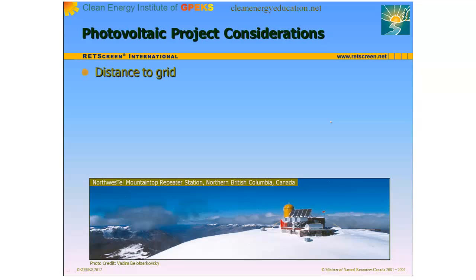If the grid is near, within a few kilometers, and the load large, more than a few kilowatts for example, photovoltaics will have more difficulty competing with grid extension. When sites are remote or difficult to access, the cost of visiting the site to bring in fuel or perform operation and maintenance tends to be high. This makes genset and primary battery systems less attractive than photovoltaic systems, which require less maintenance and benefit from automatic delivery of free fuel whenever the sun is shining.